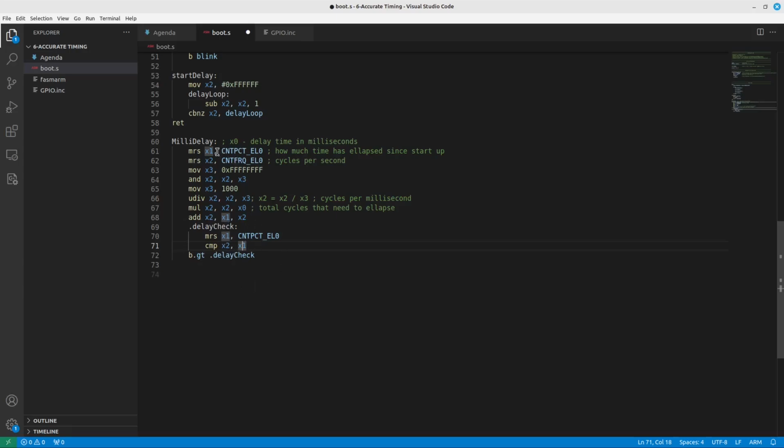Originally I said we were at, let's say, 1,000,000. We need to get to 1,003,000. So let's say we're at 1,002,000. It will check this. It'll say you're at 1,002,000, and 1,003,000 is greater than 1,002,000. So it will run this again. And let's say now it actually is 1,003,000. It will do the comparison, and it's not greater than, so it will escape. And just like here, we need to do a return. So now we have a milli delay.